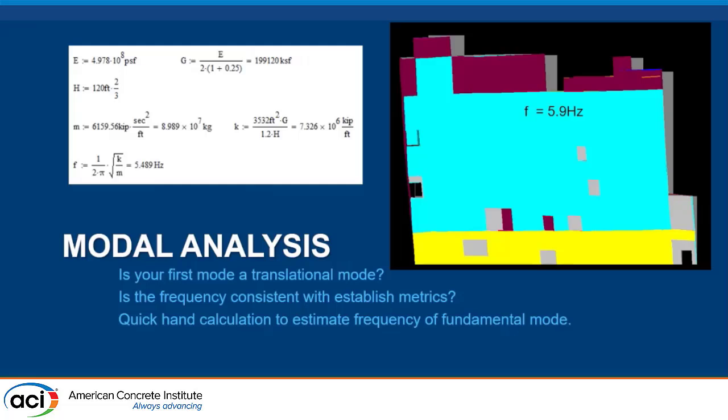Doing this modal analysis, some simple hand checks for what frequencies you expect, seeing what those frequencies are. And then when you look at these mode shapes, exaggerate them a bit, make sure that everything that you intended to be behaving together is, because you'll catch that in the mode shapes. If you thought one piece was connected or shouldn't be connected, you'll pick that up when you look at the mode shapes.